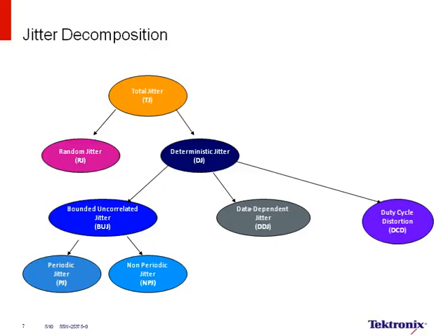So you're probably using, let's say, a TIE measurement. If you go to the TIE measurement, there should be a configuration tab, and within the configuration tab, one of the tabs should say clock recovery. And so there should ultimately be a clock recovery tab that allows you to set the various parameters for the clock recovery.